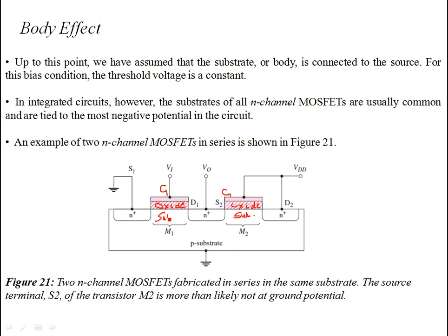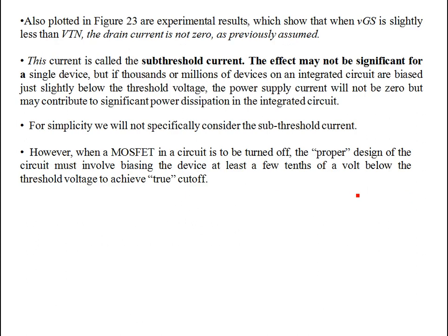But if you go on increasing the gate voltage, or this VDD, so much that the oxide breakdown occurs, then the device results in a catastrophic failure due to the short circuiting of the gate with the substrate. So that's the fourth mechanism.